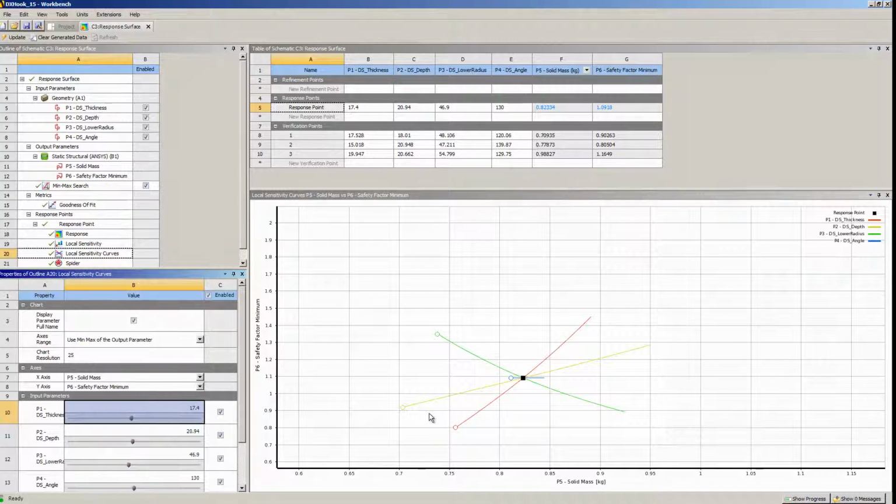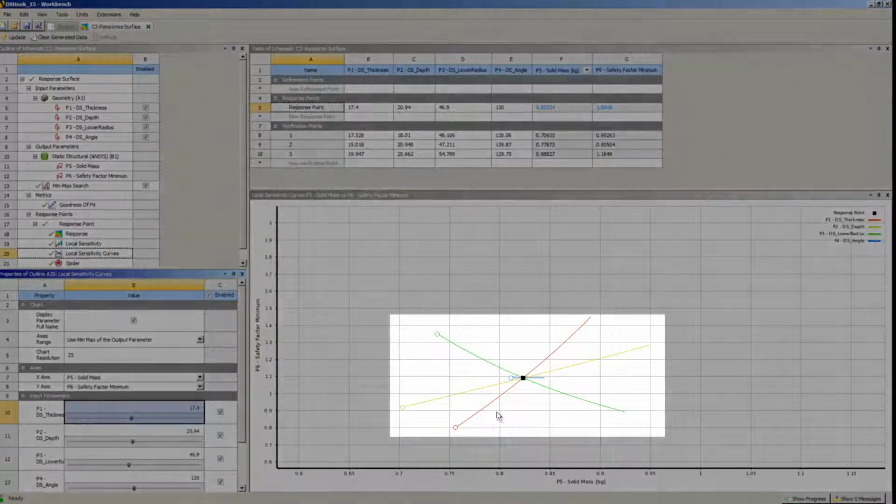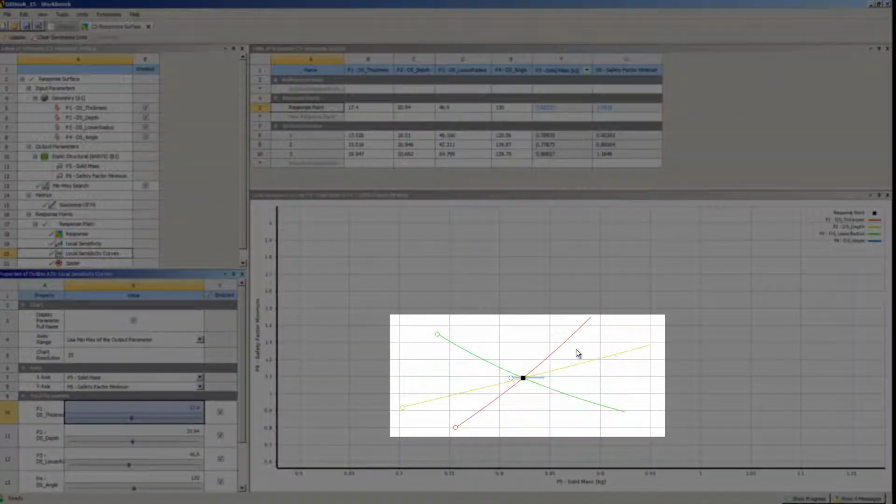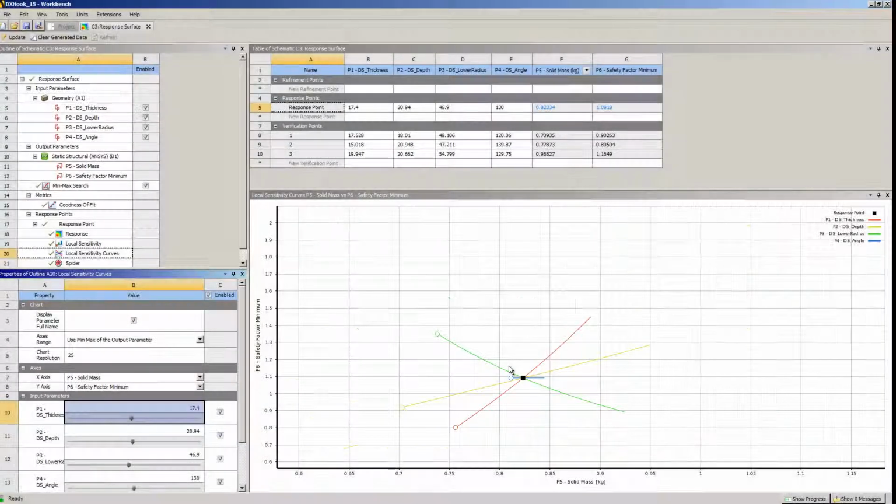In some curves, note that the rate of variation is not constant. The curve may rise steeply, then level out a little, and then get steeper again. If a sensitivity curve has a flat spot for an input, it would mean that the variations in that input would cause less variation in the output. In other words, the design would be more robust at that value of the input.